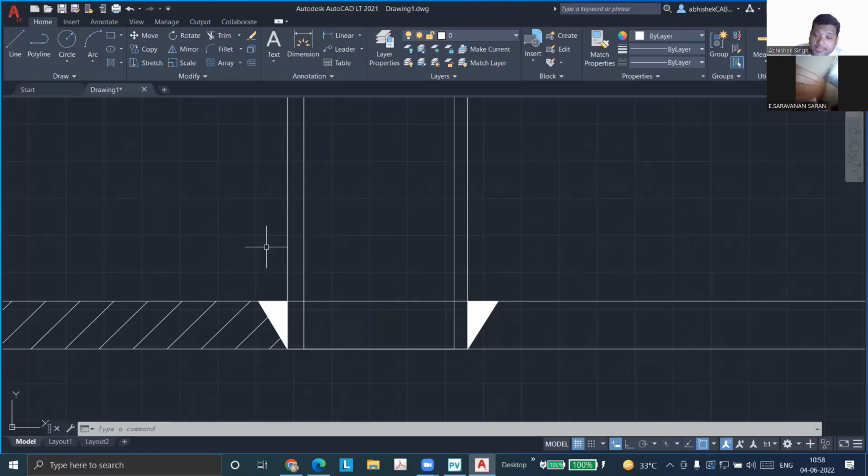Then you do the real job and try to compare. In the qualification, you may also purposefully make some faults in that weld, and you will see how they appear in the radiography. But that is a very cumbersome job, it will take too much time and money. So normally it is not done, but nothing is impossible, everything can be done. In a normal scenario, we can always say that meaningful radiography is really difficult for this case.